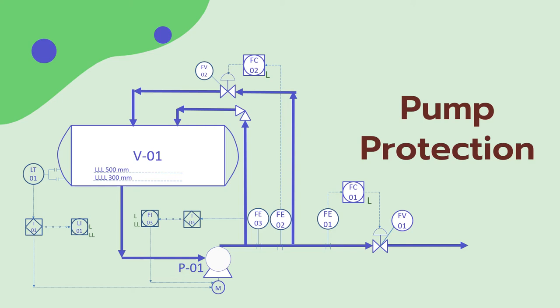This is a general concept that applies to any equipment protection. In addition to the above, we should make sure that no vapor shall enter the pump. One of the causes of this scenario is through pockets in the suction line. You may check out our course related to pipe sizing in the description to understand what pockets are. But here in the P&ID, we will just write on the suction line, do not pocket.